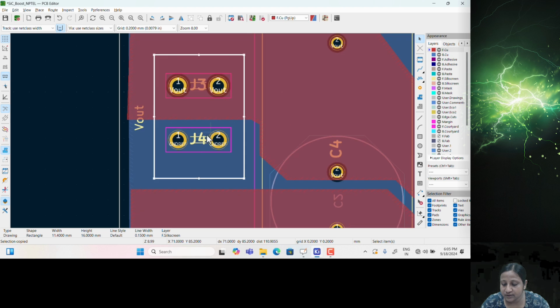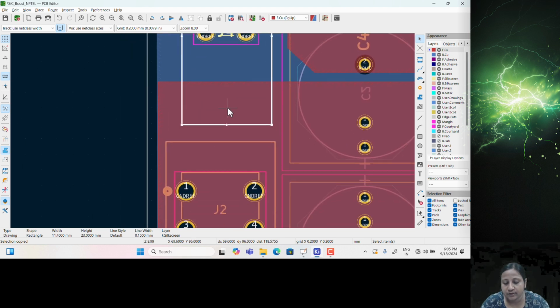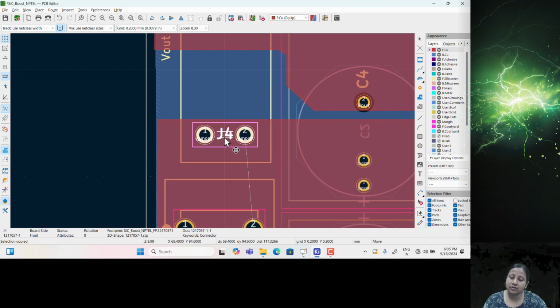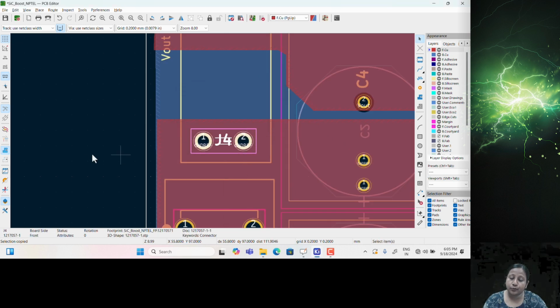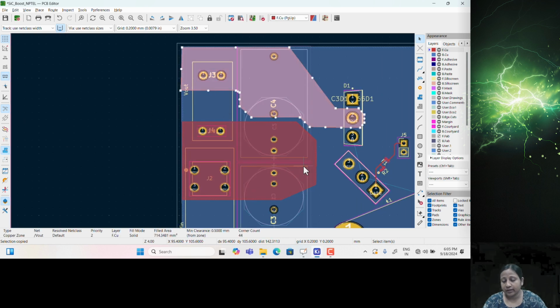So either you can connect similar to the wire connection for different resistances, or you can put this shaded portion. For the power part it is always advisable to put the input and output, like ground and the sources, in this shaded way.